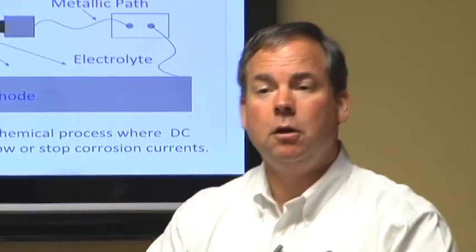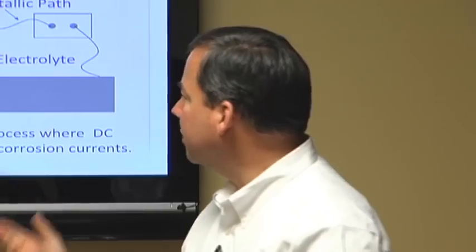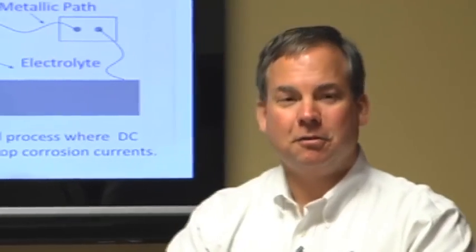So if somebody were to come to us and say, I've got this above ground storage tank and I'm worried about the corrosion of my tank bottom that's in contact with soil and the tank leaking, a very common application for cathodic protection, and you find out that tank's 22 years old and they did a survey of the floor and found 80-90% corrosion, putting CP on it probably won't keep it from leaking. In fact, it might actually encourage leaking, because as you flow current onto it, the rust particles will start to be pushed away a little bit, and now all you've got left is maybe a real thin piece of metal.